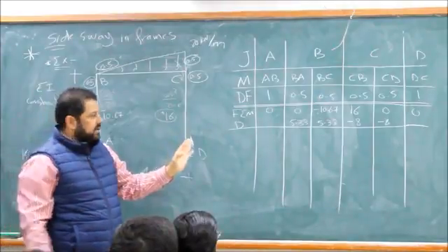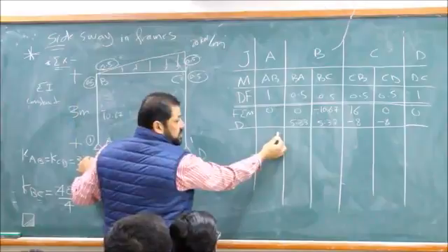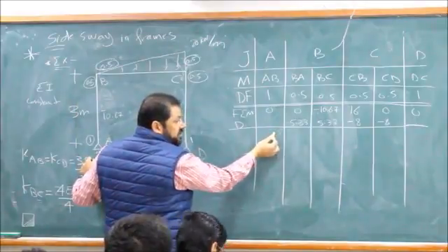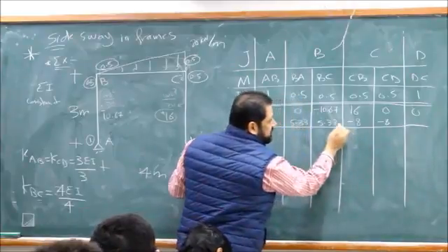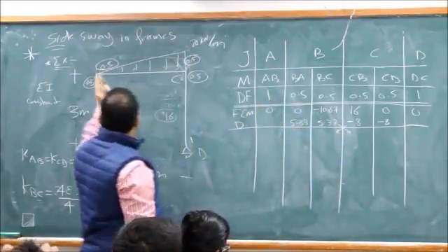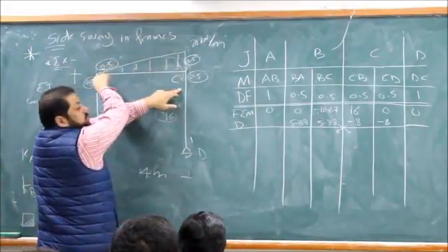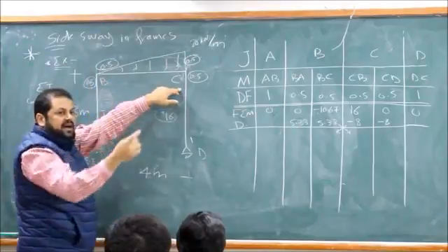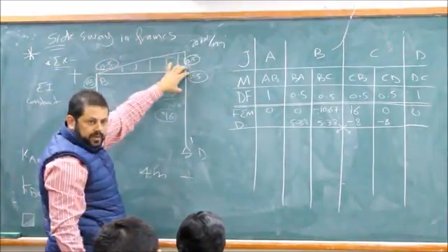Is there anything that will be carried over to this? No, nothing, because it's a pin. No carry over here. Is there any carry over here? No, nothing, but there will be a carry over between those two. There will be a carry over to this one and to this one. The carry over factor is half. Half of this will develop here, half of this will develop here.